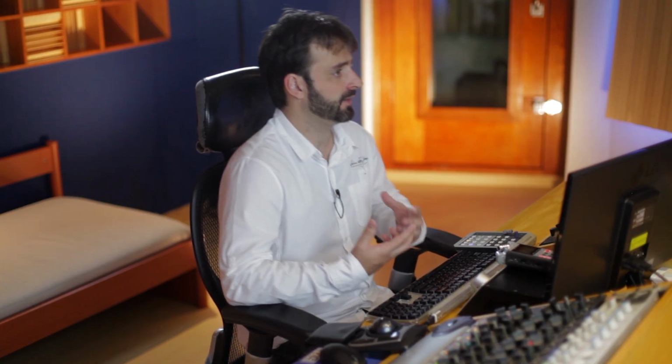This document presents some recommendations that are relevant to acoustic control room projects, and I'm going to compare them with our measurements in this control room. First thing is background noise. We know all the equipment should be powered on and should not exceed 25 dB SPL A-weighted. No two room dimensions should be equal. The ceiling height ideally should be greater than 11 feet or 3.35 meters.